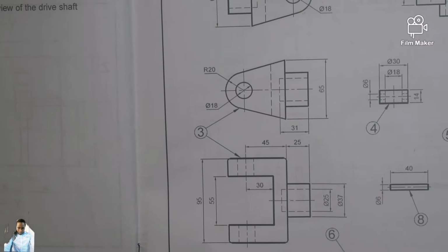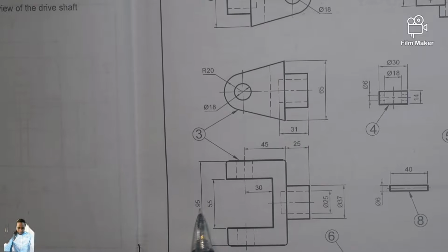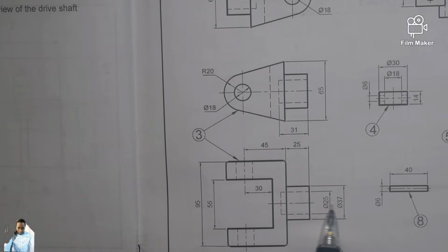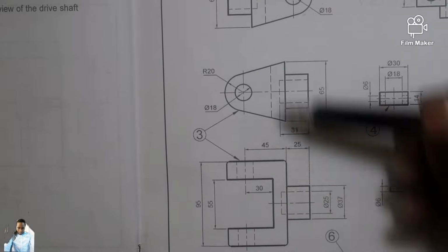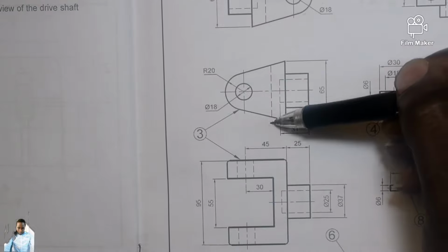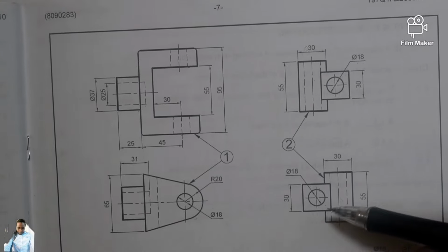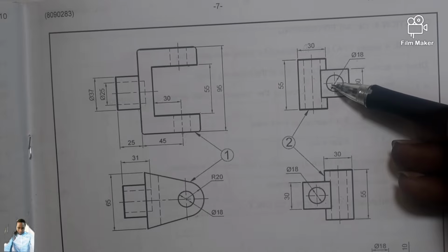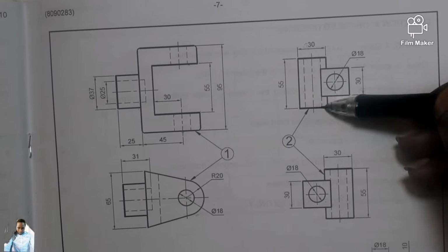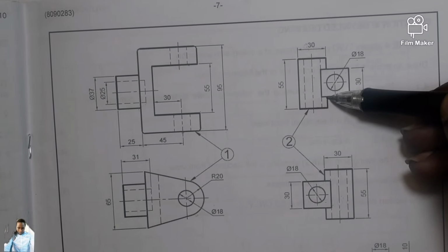Remember, if we express a full sectional front view of item 2, which means 3, the cutting plane is at the center of your item 3 on its top, so that this one will disappear. You don't have hatches here. This one will become dark. So clearly we are going to see this. We are going to see it clear, but with this one dark. From here till here it will disappear. From here till here it will disappear.